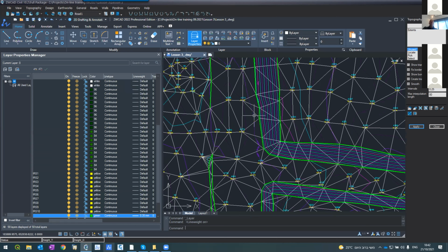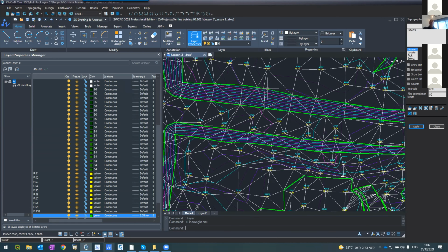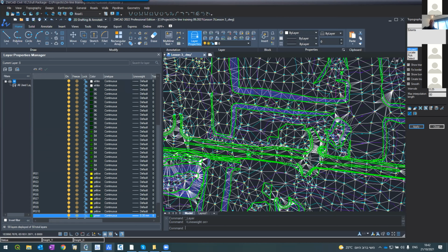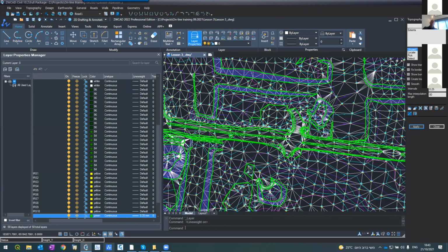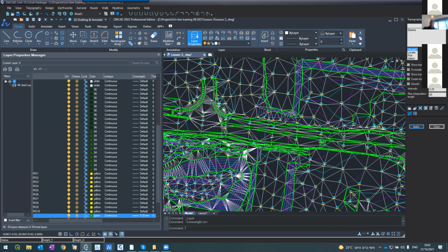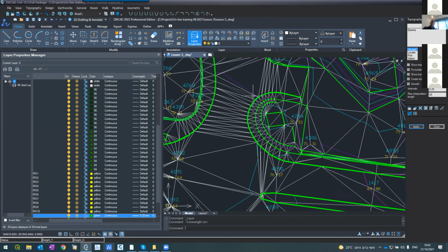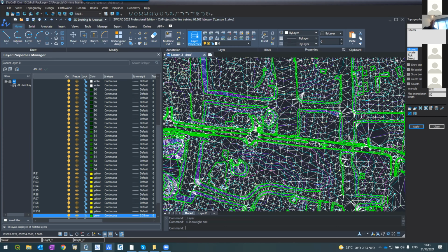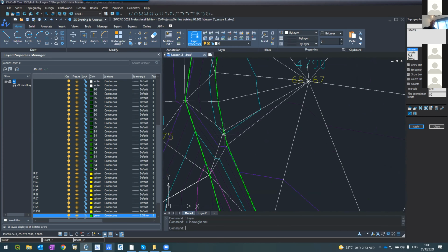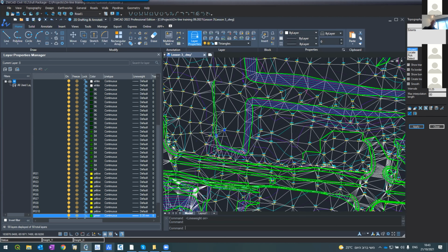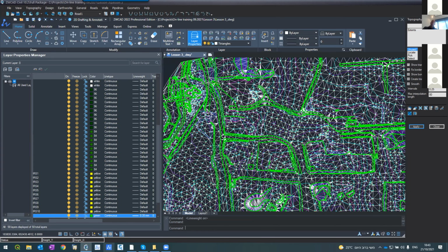Here with the break lines, you can see there's a small cliff here, a small cliff here. See here, this is a road, an existing road, I think. This is what it looks like. In the road, you see these funny triangles. It goes to the break line and from the break line, it does not cross the break lines, which is what's important for us. This is what we wanted to know. These triangles, maybe we would build another way, but because of the break line, they cannot move beyond the break line. So this is what we got.